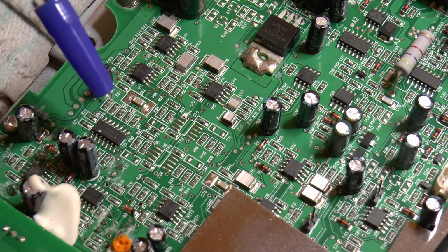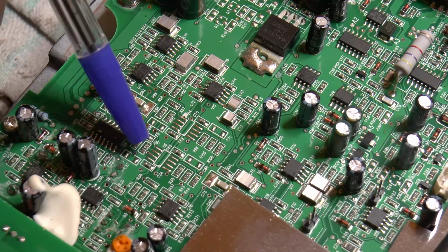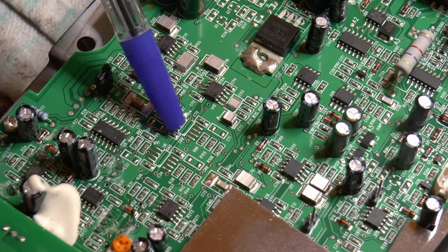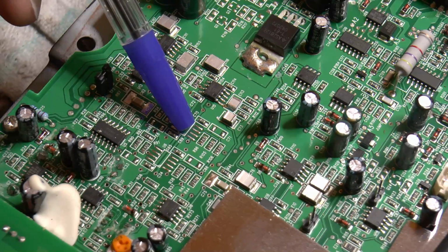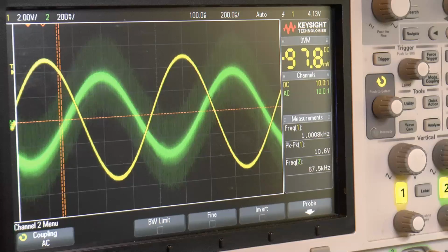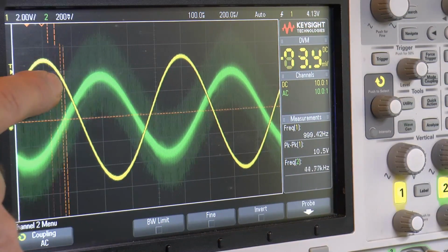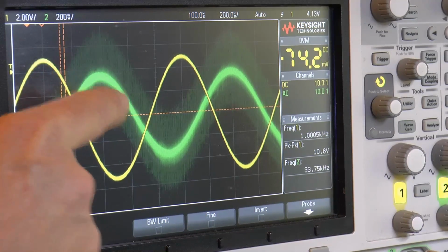But now they're actually bypassed, and there's various resistors here, the sort of feedback resistors, are 0 ohms, so they're just bypassing these 2 chips. So bypassing 4 stages, which is effectively putting this bass out of phase with the treble.